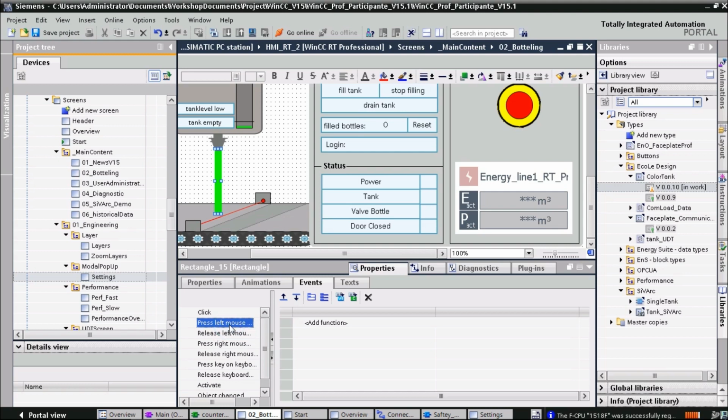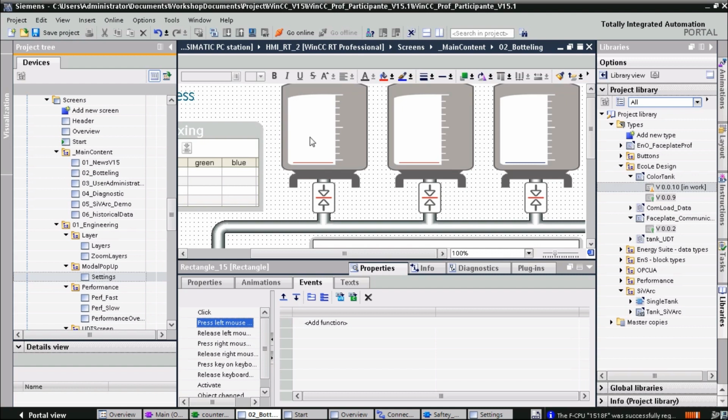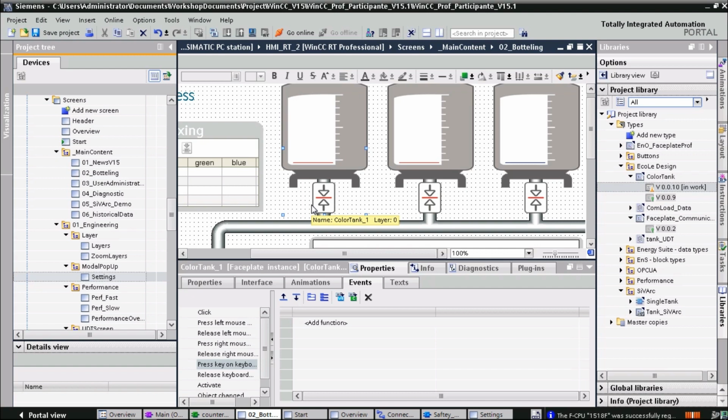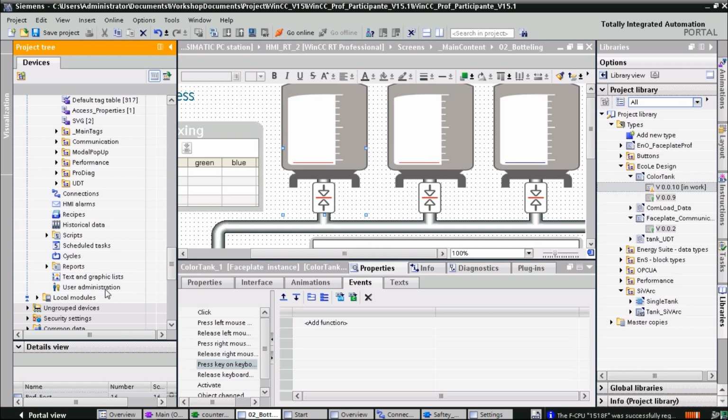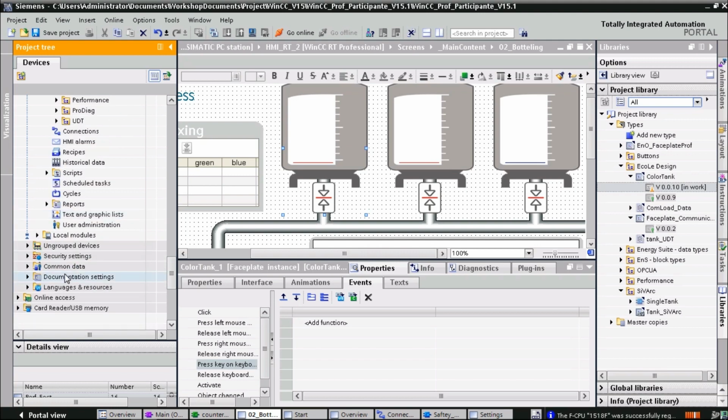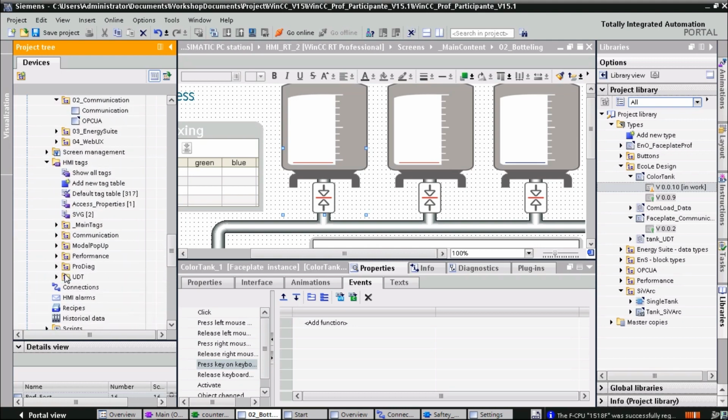So when I select my graphic I/O field, I see in my properties that I do have a graphic list connected, which is called glist valves. When I want to see what's in the graphic list, I can also just click the green arrow here, and I jump into my graphic list, which basically has those 2 graphics here. So this icon here for valve is closed, and this icon here for valve opens up. My value for 0 is icon valve closed, and 1 icon valve open. And I think that's clear. Okay. That's all I need to consider regarding the programming.